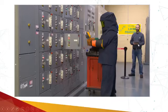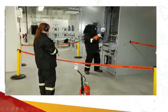There is an attendant. He could be an unqualified person or an observer, or he could be a person who is undergoing a training requirement. So any unqualified person should be standing beyond the limited approach boundary or the arc flash boundary, whichever is the greater one. Here in this case, a person is trying to operate an electrical equipment.